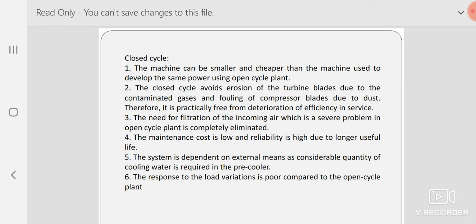You understand load falling? Say a power plant in Delhi: in winter, the load requirement is much less as compared to summer, because the air conditioning loads are very high in summer. Because of the air conditioning power loads, a lot of electricity is required. So you design the power plant for summer time. Now when you run the power plant in winter time, the load requirement falls. That time it is running at part load. A 100 megawatt power plant runs at a part load of 60 or 70 megawatt, and that time the efficiency goes down.